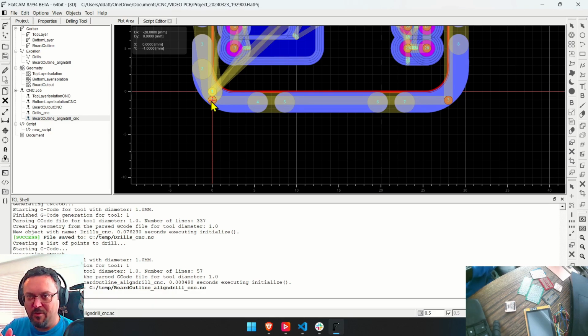And now when you move over 28 and down one, you're at where the other hole should be, this hole, and then you move it around a little bit, and then you move to the other corner. You go just corner to corner to corner, and then everything's aligned. You lock everything down, and that's when you mill it.